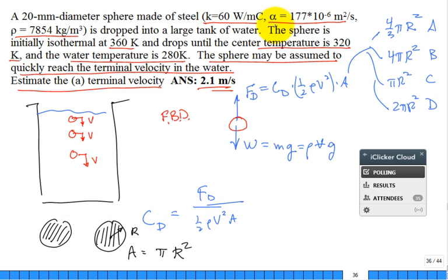Okay. Well, anyway, it's fluid mechanics. You're going to lose points because of fluid mechanics, not because of heat transfer. That's why you're going to lose points, aren't you? Okay. So then you have this area here. You get the drag force. What's my last force that I need to include on this free body diagram to get the terminal velocity? Buoyancy. So there's an additional force like this, and it's the buoyancy force.